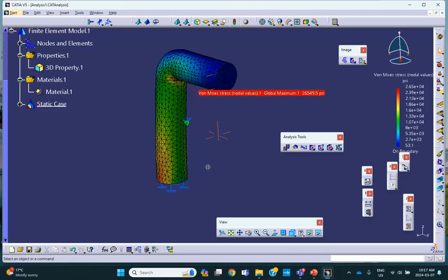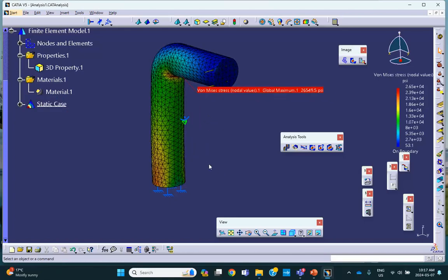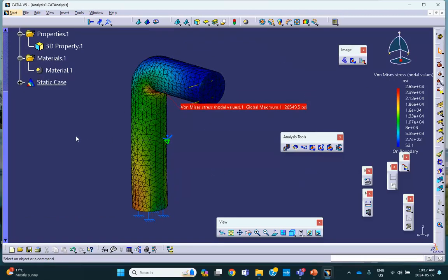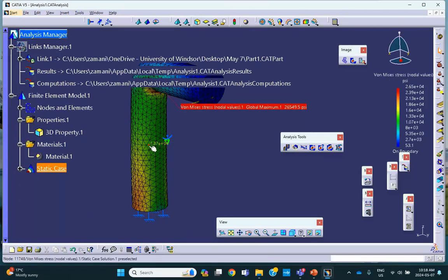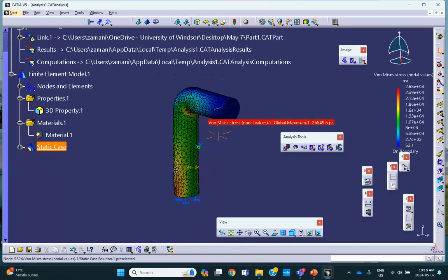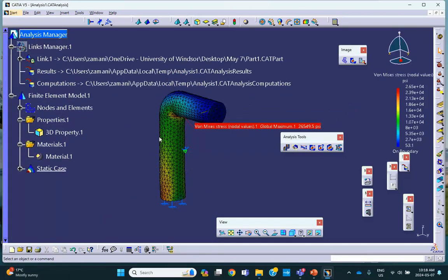So remember, garbage in, garbage out. You are responsible for assessing the validity and the fact that these make sense. And the only way to know that is what is called mesh sensitivity analysis. Because does this analysis depend on the mesh? If it does, these numbers are totally nonsense.